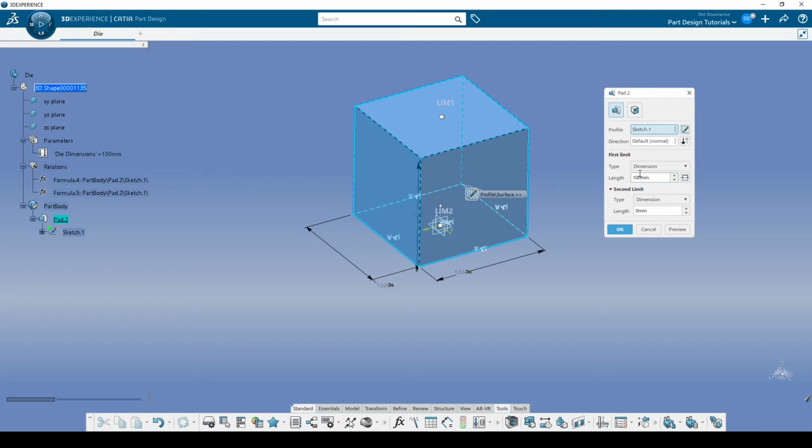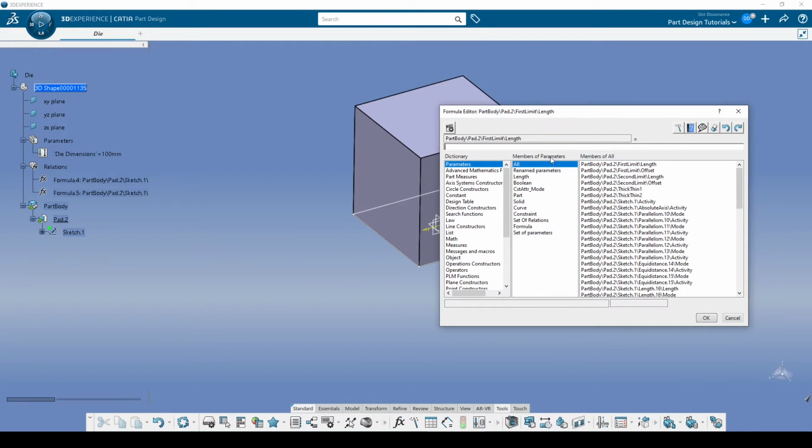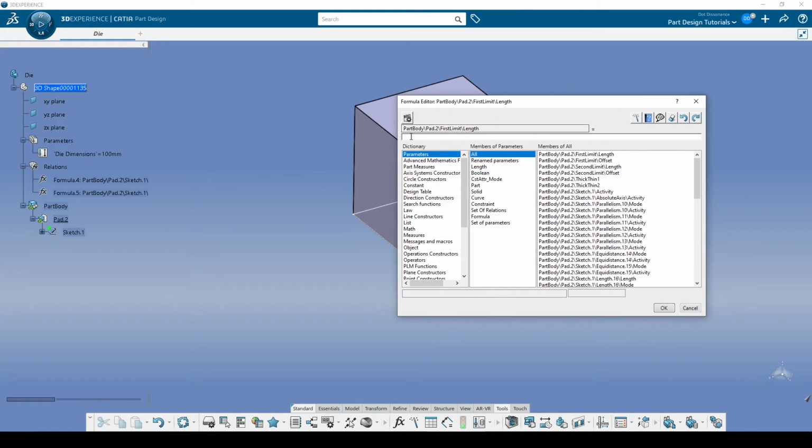But if you just can't get it to work, maybe in the future when you watch this, everything will be fixed. Dassault has been pretty good. Every couple months or so they've been updating things. What you can do to fix this is you just go straight to the formula section. So right on any field here, right click, and then you'll have the option to edit formula. So you go there. And now, again, remember, this is equal to whatever is here.